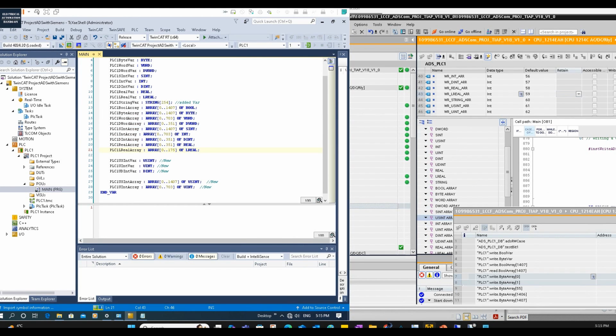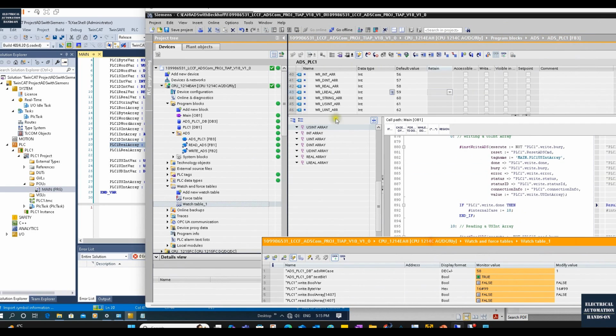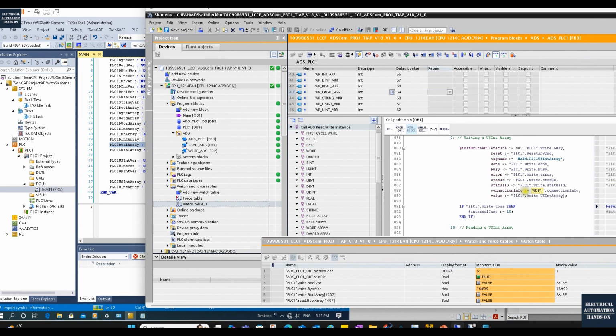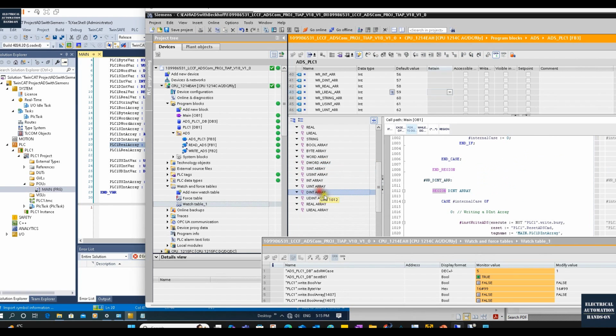In the real case, definitely you do not have this huge area. You just typically pick the bytes, integer, and the real, right? Roughly, that's enough. So it can save a lot of time. So basically, you can bypass some scrolling, modify some of this FB3 read and write to jump over the area for some data types. You do not have to do that. For example, D word, maybe the dint. You do not have to send and read and write for this area. Then you just jump over it and maybe comment out this area.